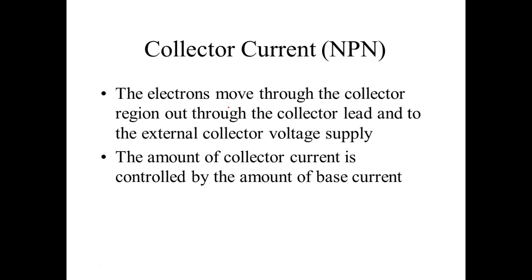But it's going to have a lot of resistance. As I keep increasing that base current, the valve opens and lets more current through until I get up to the maximum flow, which we call saturation. And basically, the collector resistor, or the loads you put in the collector, and we can put all kinds of loads in the collector, guys. Here we're putting a resistor, right? We can put all kinds of loads up in that collector.